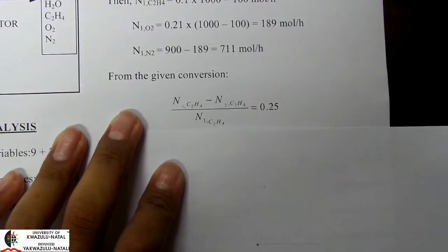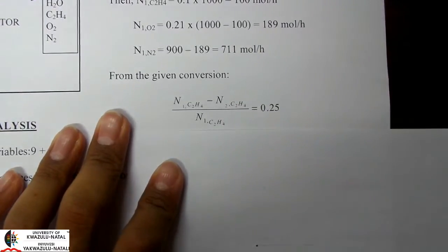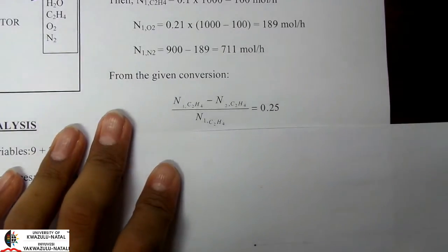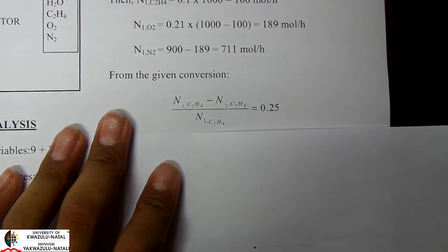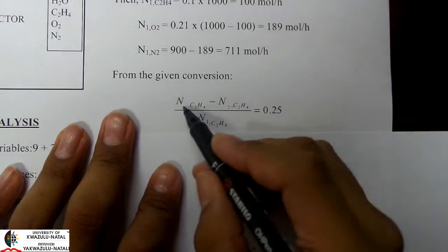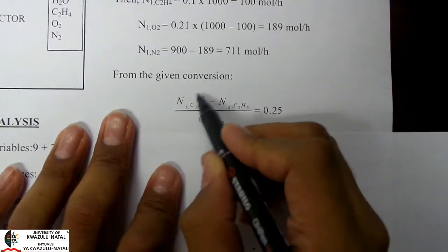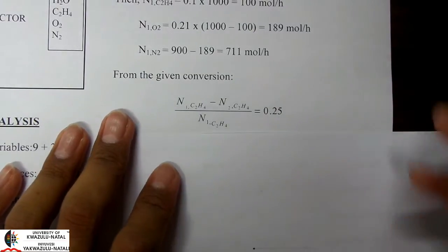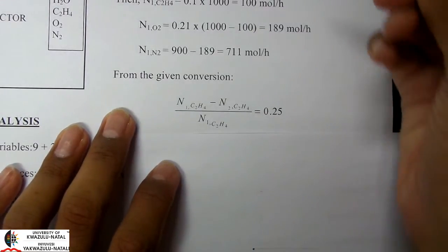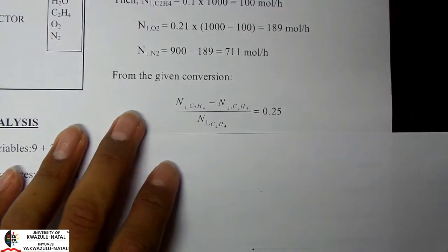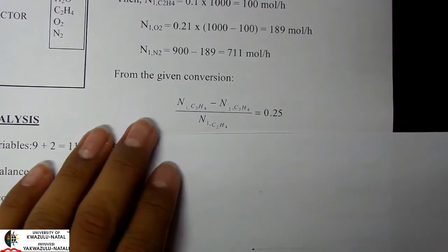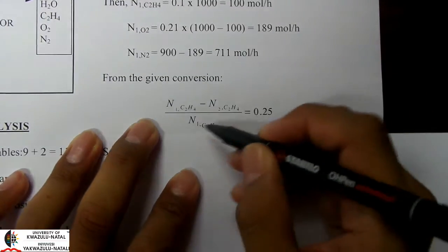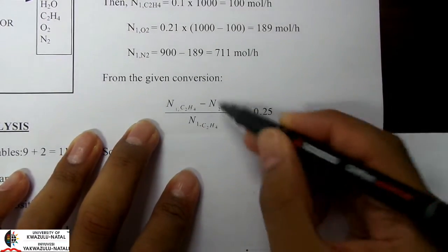Okay, and remember that when we are talking about conversion, it doesn't really matter how many reactions we are looking at. Conversion strictly deals with whatever reactant is coming in and whatever reactant is coming out. Okay, it doesn't specify how the reactant was converted, in which reactions or any of that. It is simply an input and output relationship, and this is it given here.